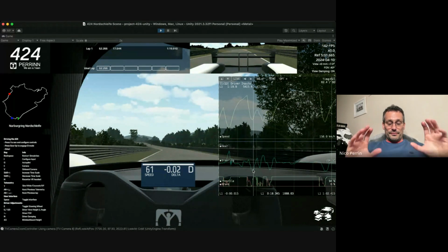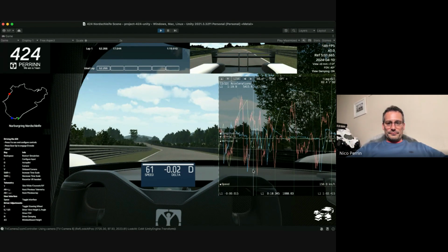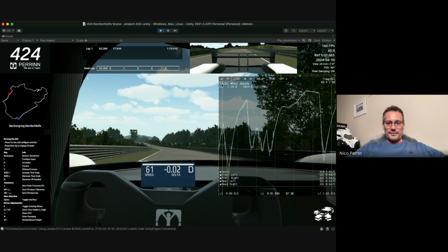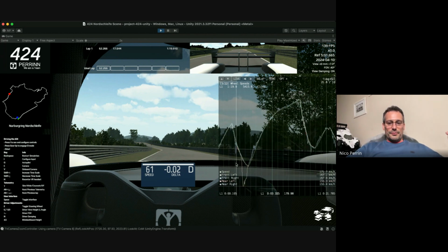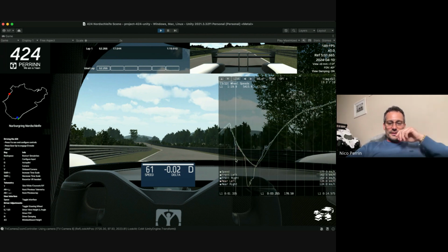For me, the big rule of looking at data, obviously the driver will tell you when he has issues, but I love looking at the wheel speeds, individual wheel speeds. So let's have a look. It's on page 3. These are 4 individual wheel speeds. And that's when you start noticing potential problems. So I tend to always say 4 wheel speeds tell you 90% of the story.